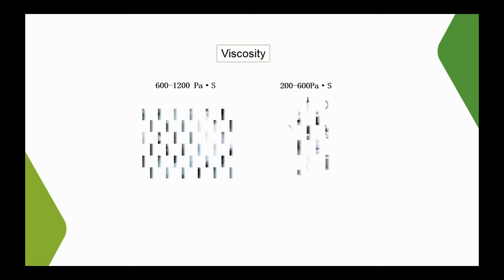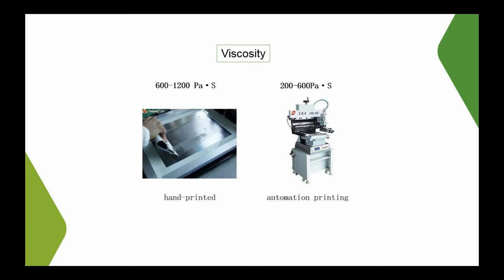In the SMT workflow, there is a process of moving, placing or handling the PCB in the middle, from the laser stencil plating of the solder paste and attaching the components, to the reflow heating process. In this process, in order to ensure that the plated solder paste is not deformed and the components attached to the PCB solder paste are not displaced, it is required that the solder paste should have good viscosity and retention time before the PCB enters the reflow soldering heating.